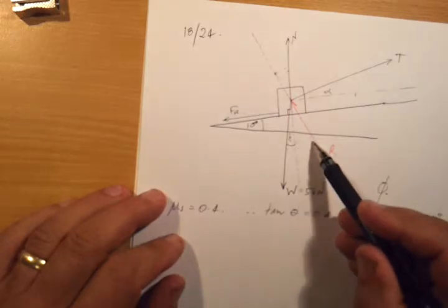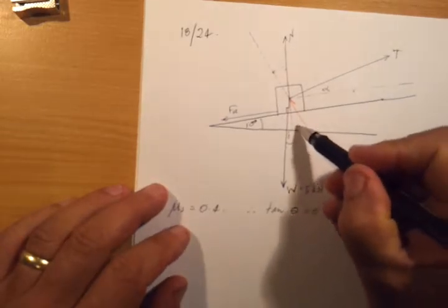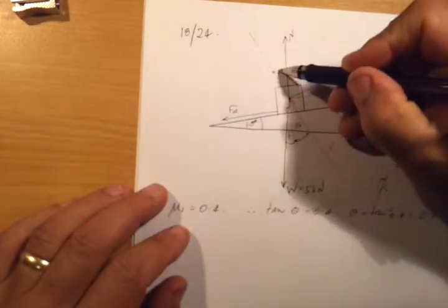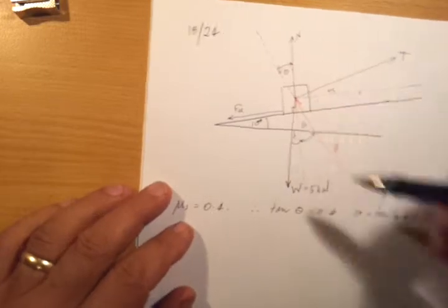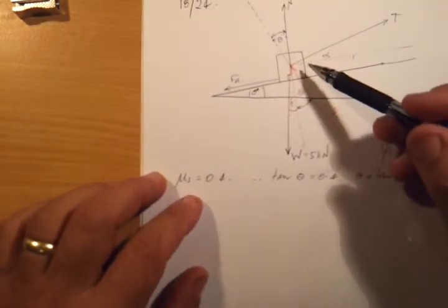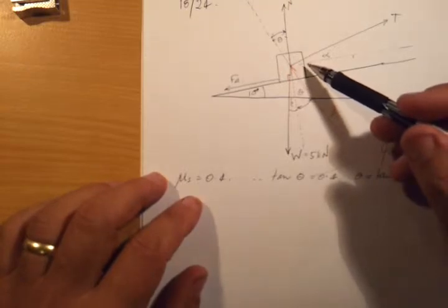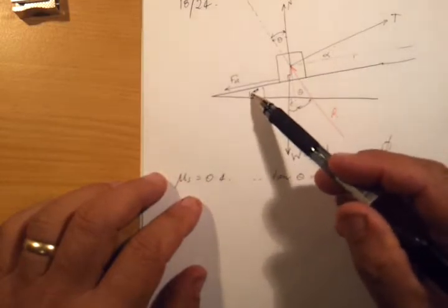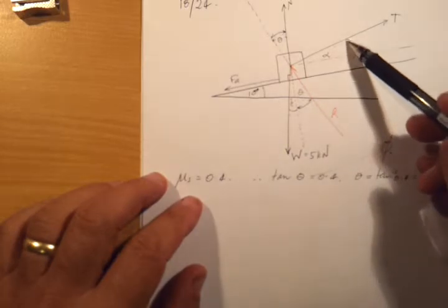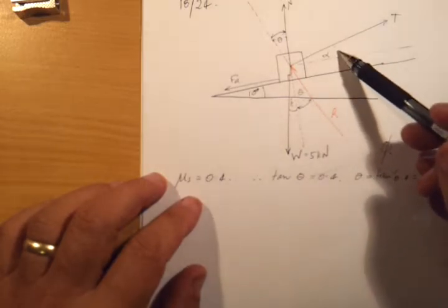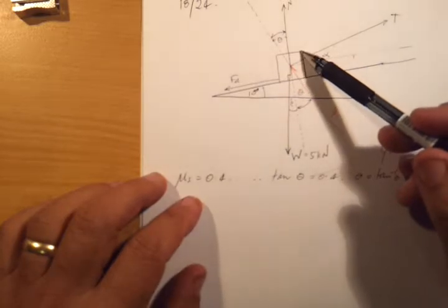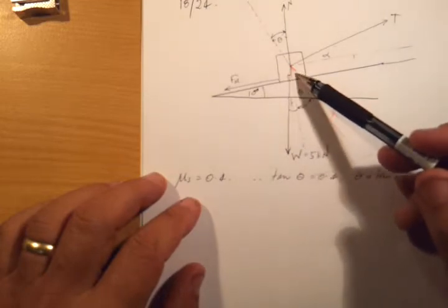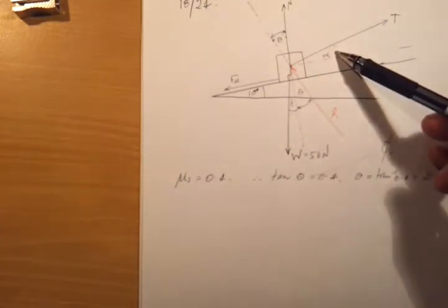That. So this will be theta, same as up here, which will be the angle of repose. And why is it the angle of repose? Well, it's the angle of repose because we've been told this object is just about to slip. It's just about to go. And although this angle of the plane is fixed, the fact that we've got an extra force here acting at another angle provides us with a changing angle causing this object to start to want to move. And later on we're going to work out what this angle is.